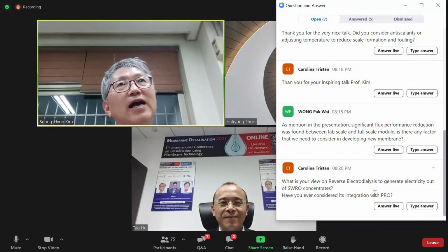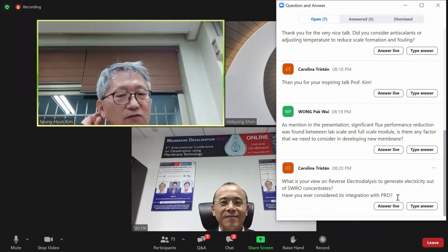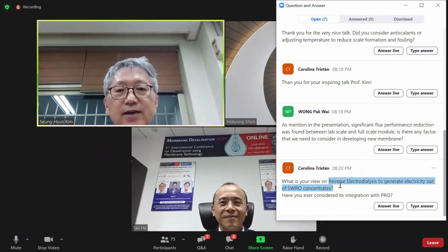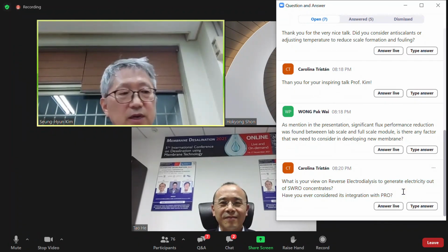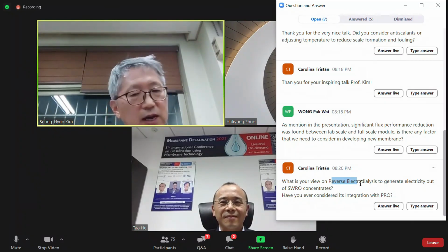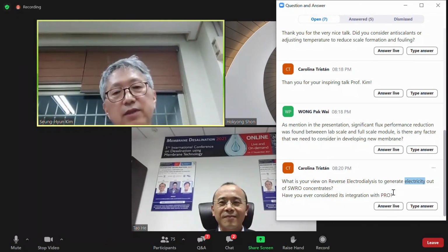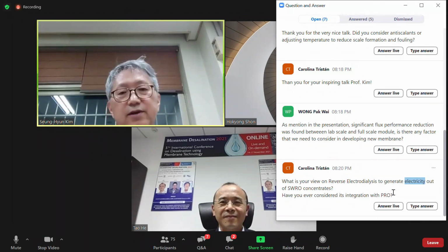Fibers. I like to have long fibers, high flux, and lower heat losses. That is the key point of membrane distillation. Our fiber is 45 centimeters long. I like to go for longer fibers, but because of the temperature drop, I couldn't go that far. So if you develop fibers that maintain high performance while losing little heat, then it's good. I think that is the first direction to go.